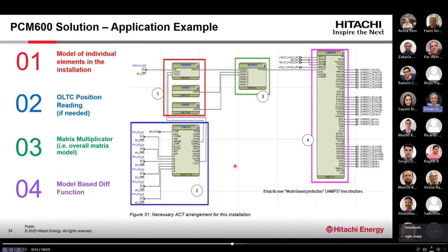How will we model this? We'll model it by one variable shunt reactor model and two line section models. We have several models available. One is for variable shunt, one is for fixed shunt, one is for series impedance. Therefore, three different types of impedances, and then line section.